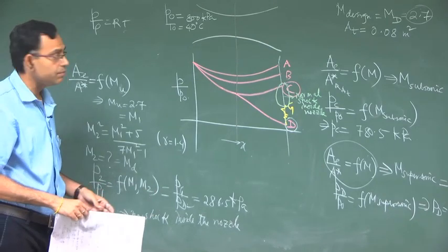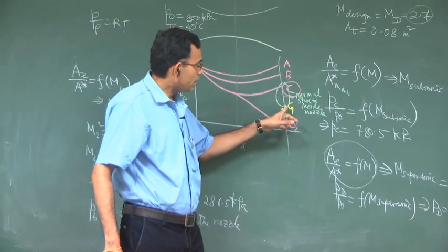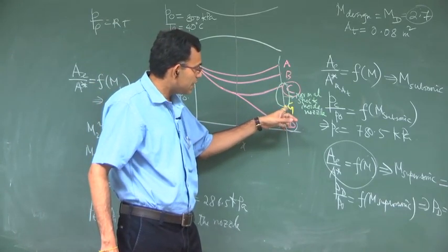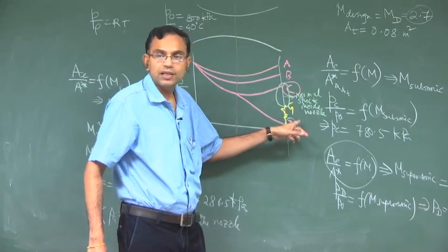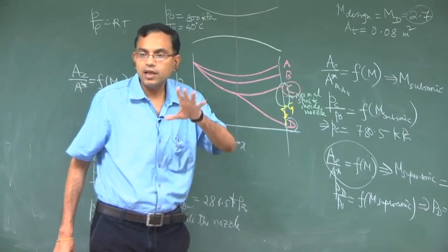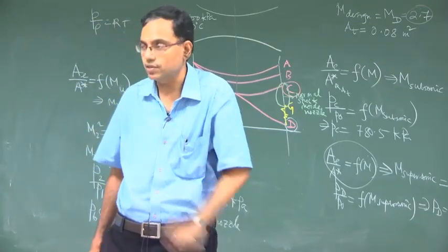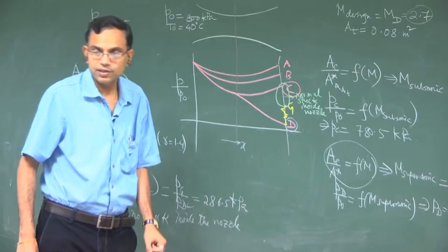Yes, Pb less than Pg. So, for pressure less than G, all the shock will be outside the nozzle, right. So, no shock inside the nozzle means the question is there is some shock, but shock only outside the nozzle, that is the meaning of the question.